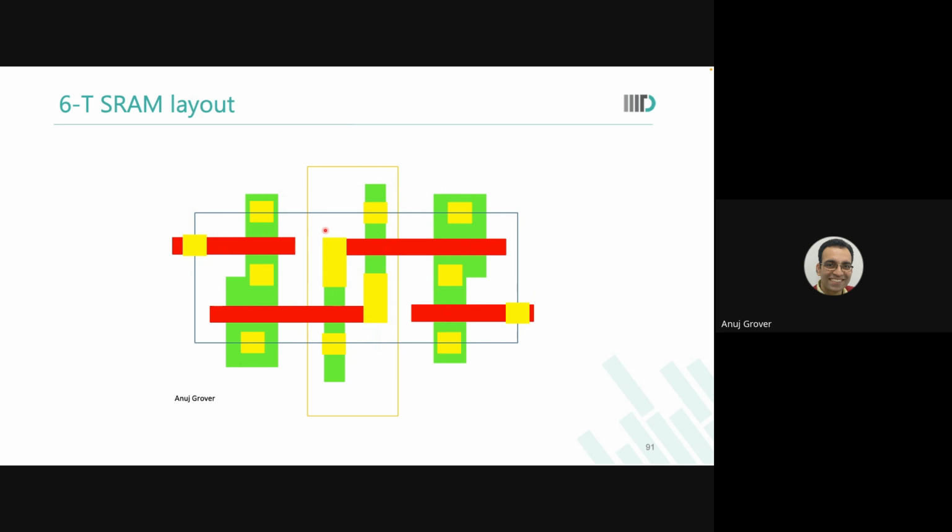So that feature isn't there at all, because as soon as you leave that little line over there, the lithography machine will go bonkers. So forget it, I will make a long contact. So long contacts are allowed because these two nodes were anyway wanted to be shorted. And for memories, area is diamond.